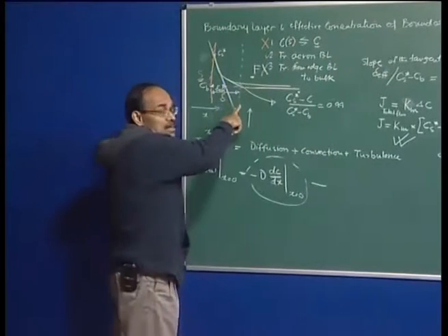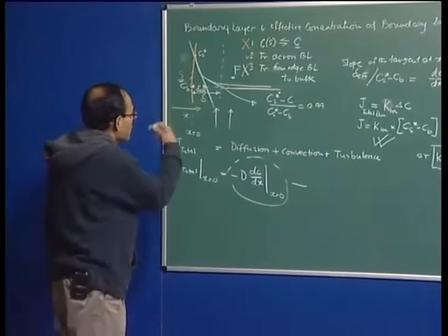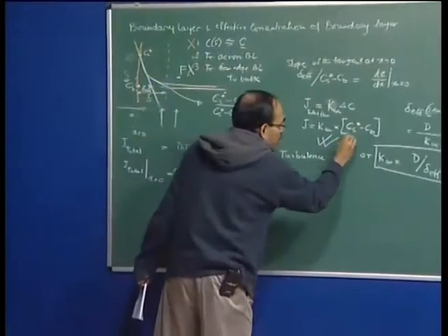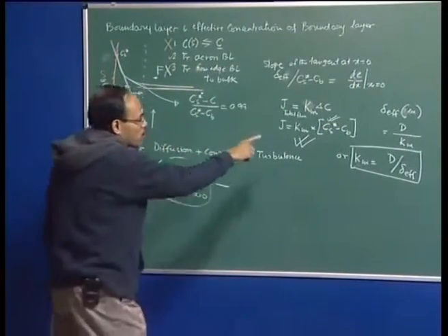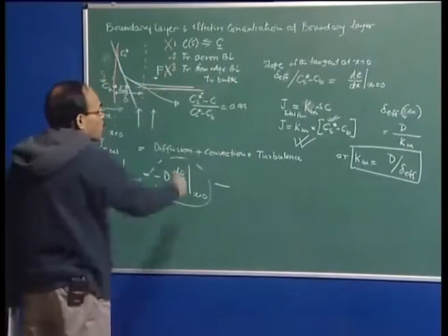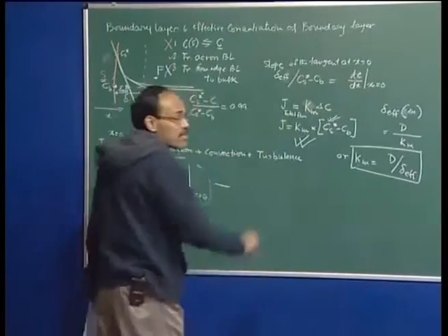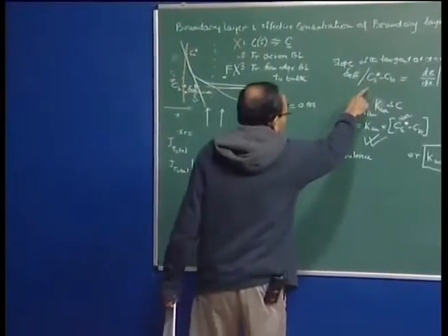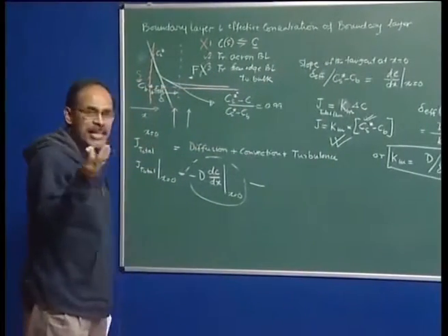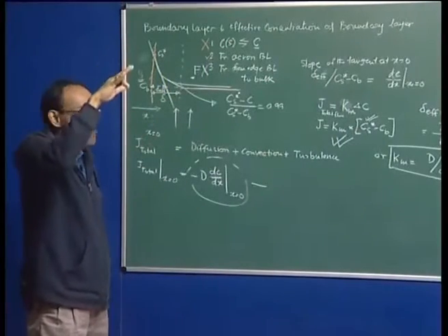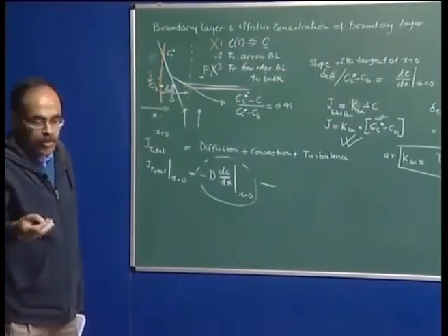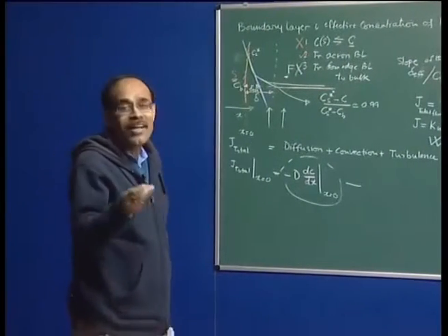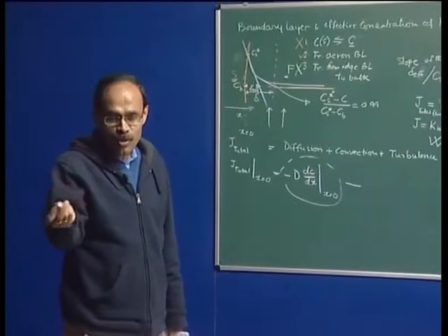So, at the temperature where I carry out the measurements, I can find out very easily the saturation concentration level, and therefore the surface concentration can be known. The way the surface, or interfacial, concentration during boundary layer mass transport is calculated is simply by the application of equilibrium concepts, and in this case the saturation concentration is the surface concentration. The bulk concentration of course can be taken to be 0, or it can be taken to be changing with time, depending on whether the reactor size is much bigger than the dissolving species or not. For example, if I am talking of a 150 ton steel bath and I have added 2 lumps of ferroniobium, I can consider that the bulk concentration of ferroniobium possibly is 0.001 or 0.01 percent, and I can ignore it.